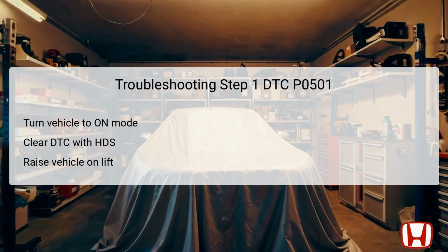It's essential to ensure the vehicle is raised securely on a lift, allowing all four wheels to rotate freely during testing. Proper vehicle support ensures safety while performing diagnostics. This initial step sets the stage for confirming whether the issue is still present after clearing the codes, thereby allowing for a systematic troubleshooting process.